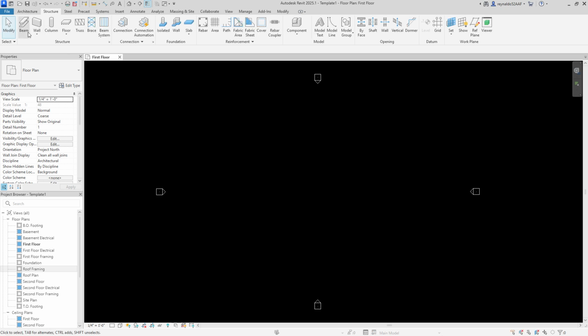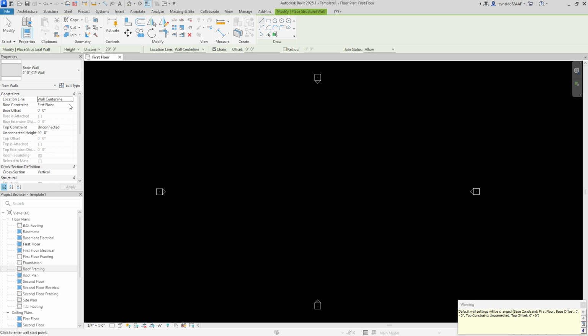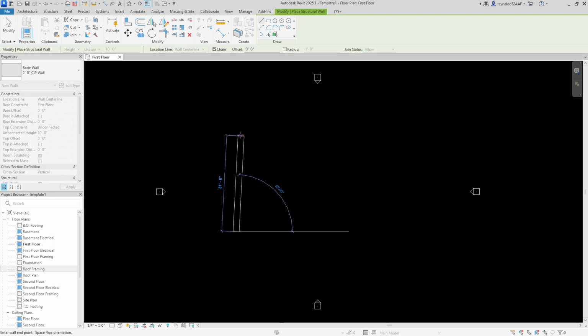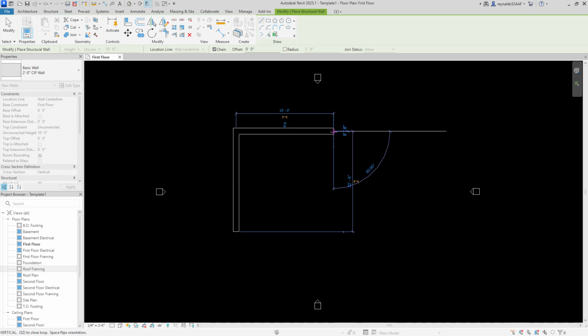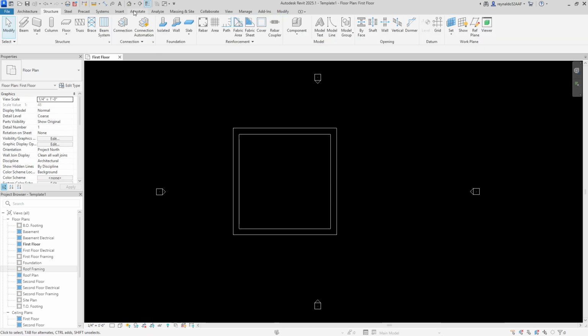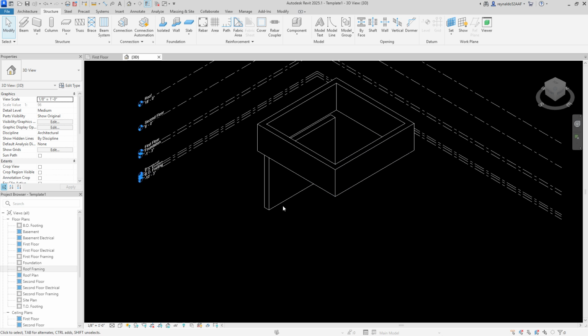So when we go back again to my structural wall, for here we want to go not depth, but we want to go height. And for the height, we're going to choose 10 feet. And now we can actually draw our walls. There we go. Now I'm going to go to the 3D so you get a view of these walls here. Delete that one, and there we go.